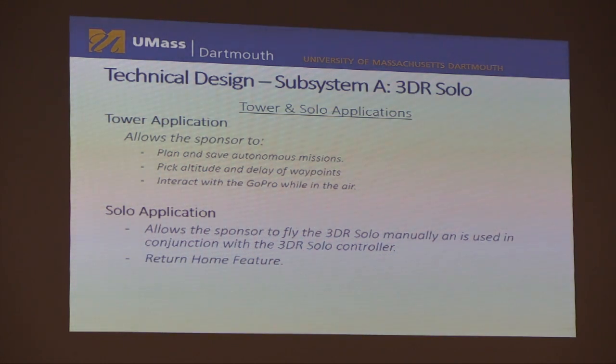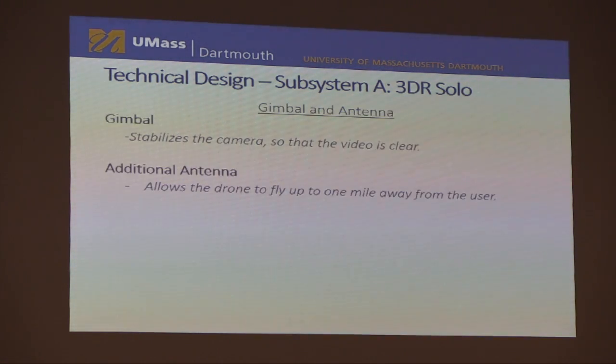We only recommend that the customer uses the manual version of flying the drone if need be. So this would only be if the drone was going to land on something that wasn't flat. We would ask that they pause it mid-air and land it themselves, because sometimes we had an incident where the drone flipped over and all the propellers broke off because it didn't realize that it had landed, so it didn't stop.